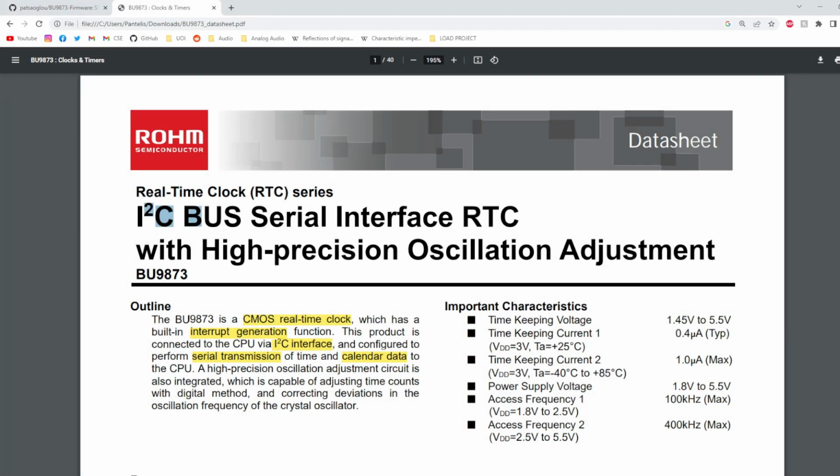So let's get started. When we write a driver for a peripheral we don't know about, it's a good idea, before we focus on the stuff we care about, to browse carefully through the whole datasheet, and once we do that, to focus on the necessary stuff. The necessary stuff that you have to look for is what communication interfaces the peripheral uses, which can be more than one, because the peripheral might use one to initialize and one to communicate and interface data with the microcontroller.